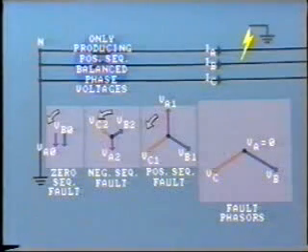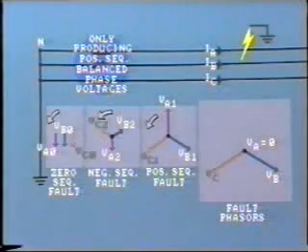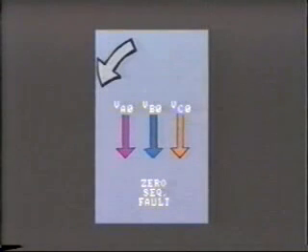Similarly, with the C phase voltages. The phase voltage VC at the fault is obtained by adding VC1, VC2, and the missing component VC0. Now, another interesting factor becomes apparent. The V0 components in each of the phases are of identical magnitude and all are at the same phase angle.